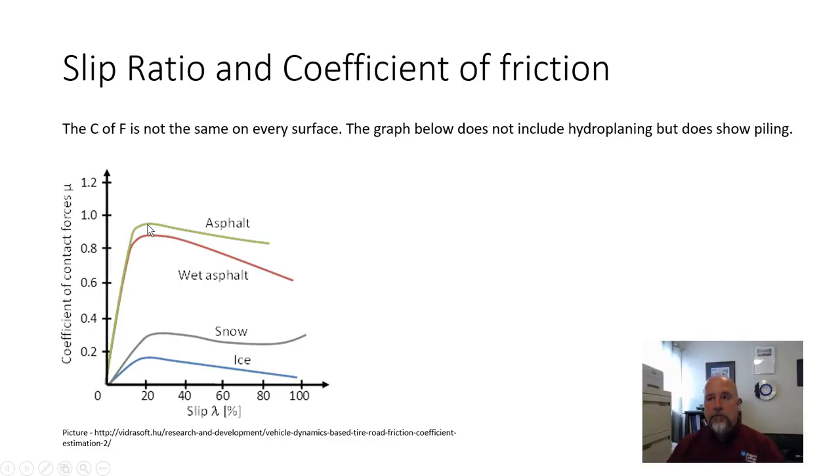Previously I said, static friction, kinetic friction. What actually happens here is with a very small amount of slip, you're scuffing rubber off, you're tearing little pieces of rubber off the tire. That warms the rubber, and it exposes fresh, clean rubber to grab the ground. So you do get an improvement up to a point.